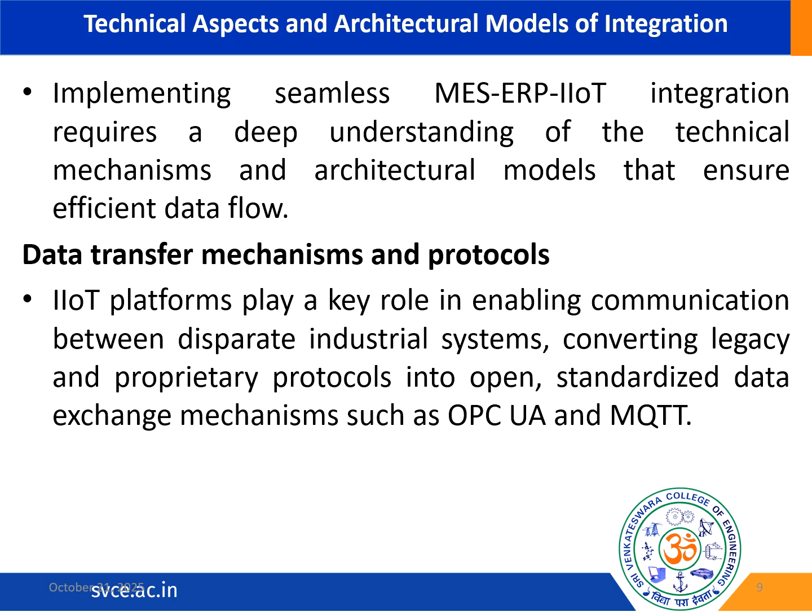Next, moving on to the other protocol, we call it MQTT, Message Queuing Telemetry Transport. This MQTT is considered to be a lightweight messaging protocol. MQTT is suitable for unstable networks. It buffers data in a broker, and it ensures reliable delivery even with communication interruptions. So it forms the basis of many industrial data streaming platforms.